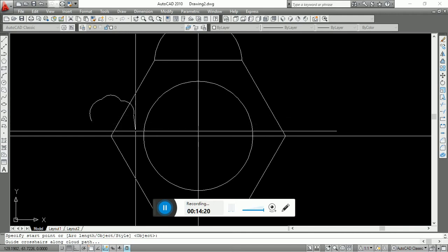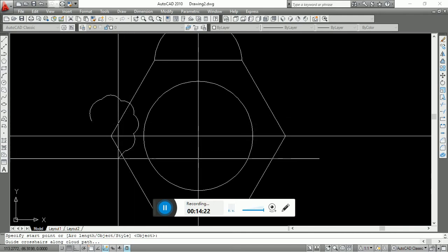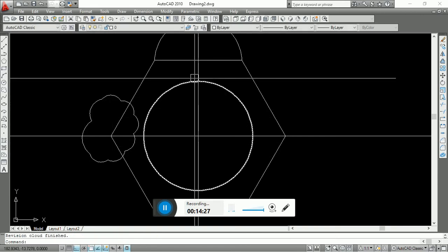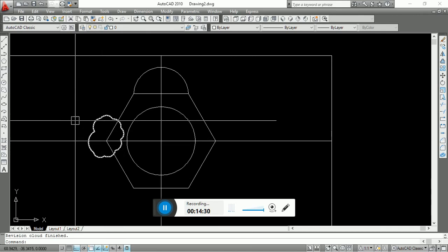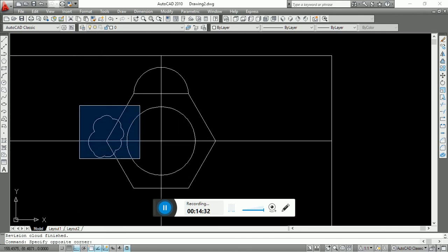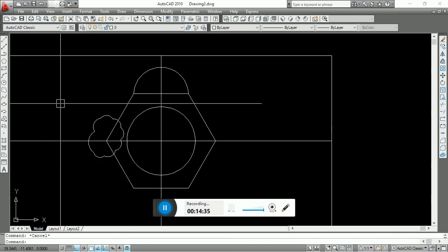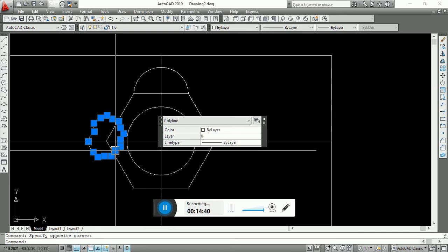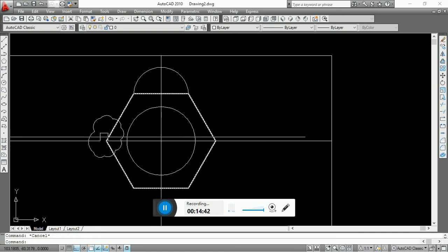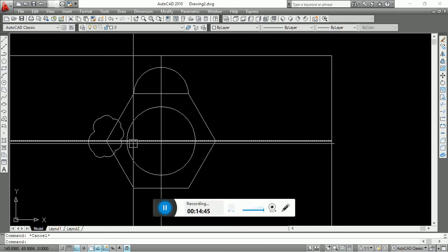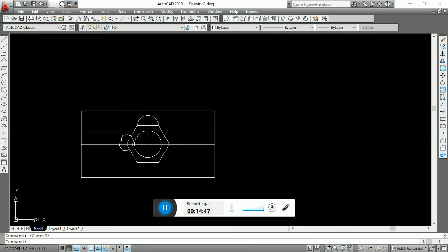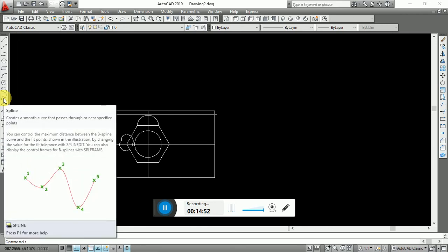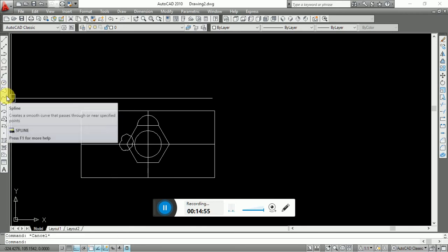Just left click anywhere in the window using the mouse and move your mouse like this. Okay, it is important for detailing in drawings. If something is on hold or something is very important, then you can show this revision cloud on that detailing, so it will be easy to see the detailing. Okay, now I'm going to show you a spline. It is a random spline.